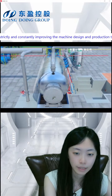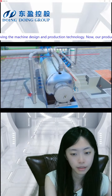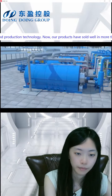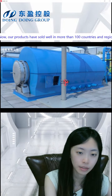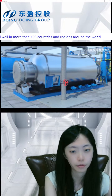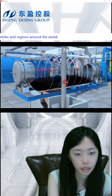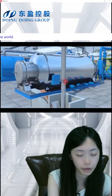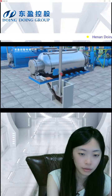Or some oil-based rock chips, or steel mill waste, steel mill oil sludge. Well, we have many kinds of oil sludge. The design of this project is different depending on the raw material. For example, we have different pre-processing to lower the water content. Use a centrifuge or filter press to dry the water.